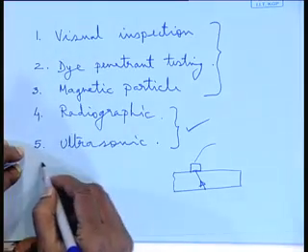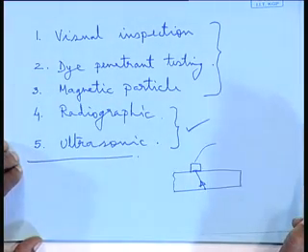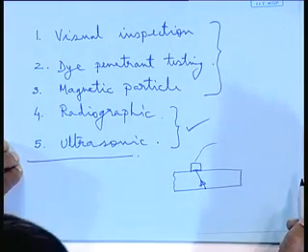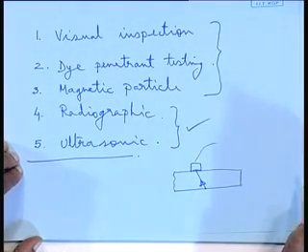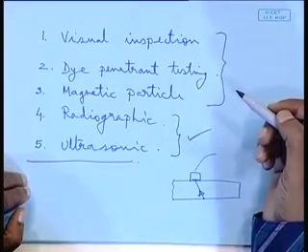So, that is how we see these are the basic 5 techniques which are used extensively. What is done is, the vulnerable parts, say the bilge plate, that welding of the bilge plate and the side plate, the shear strake and the side shell plate, such vulnerable joints are 100% radiographic tested.